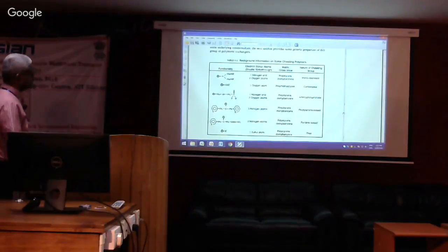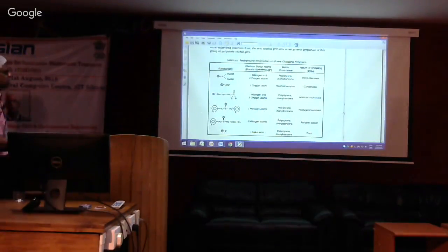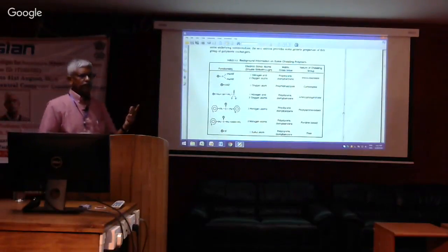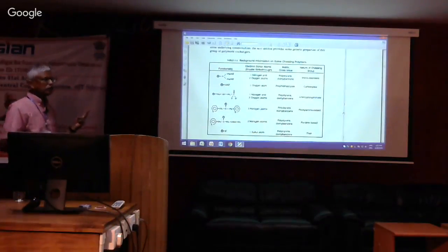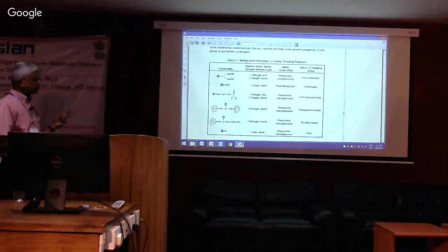Then we can have Dowex-3, and remember I was talking about the other day when we were talking about phosphorus, this is the starting resin that we use, into which we then put iron oxyhydroxide or zirconium oxide or whatnot. And we can have Dowex-2N, this is pyridine based, or we can have thiol, which is what we typically do for mercury and silver. If you have to remove mercury and or silver, your first choice would be a thiol.